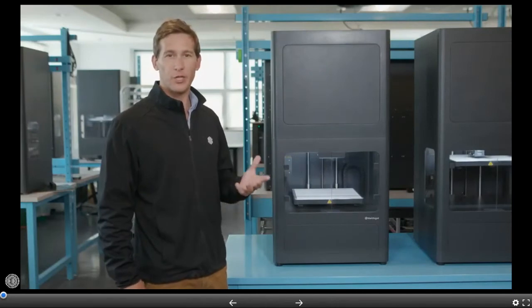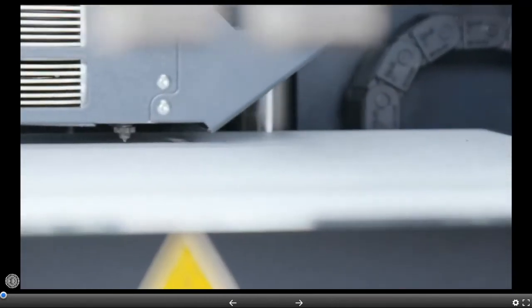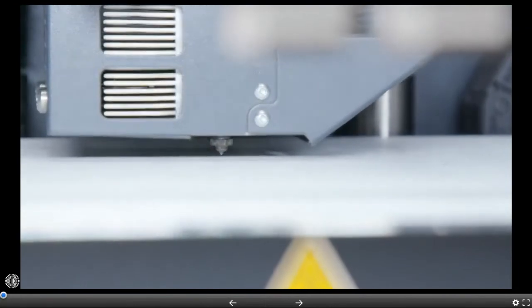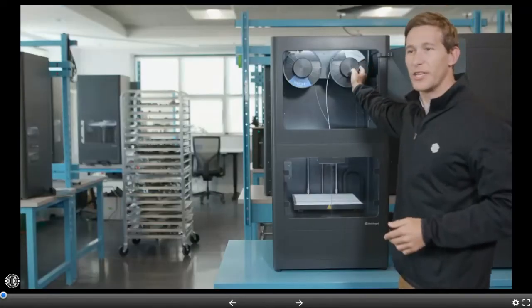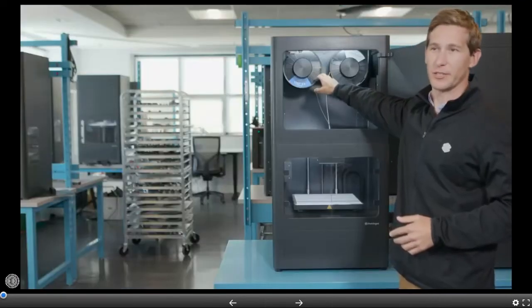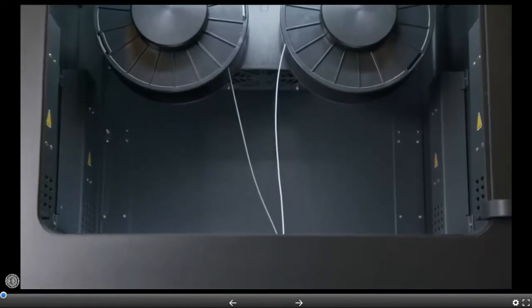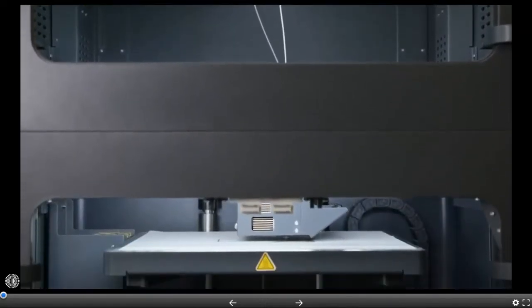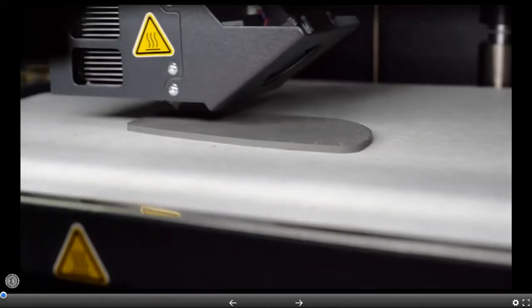Before starting a print, the machine automatically maps and levels the bed to ensure the first layer goes down well. Your print is built of 2 materials stored in this heated chamber above, one of a ceramic release material and one of the metal to be printed. This filament material is metal powder safely suspended within a 2-part plastic binder. It gets heated and extruded onto the build plate where the part is created layer by layer.